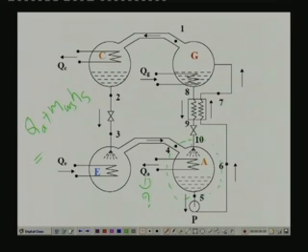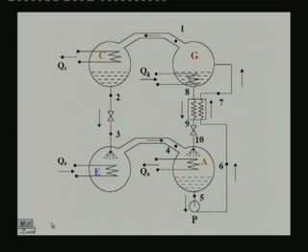This should be equal to energy coming in. So, energy is coming in by the way of mass flows. So, energy coming in is m into H1, this is nothing but the energy contained in the refrigerant plus m strong solution into H10. So, this is the energy balance for the absorber. So, from this equation we can find out QA, because we know all these mass flow rates and enthalpies.